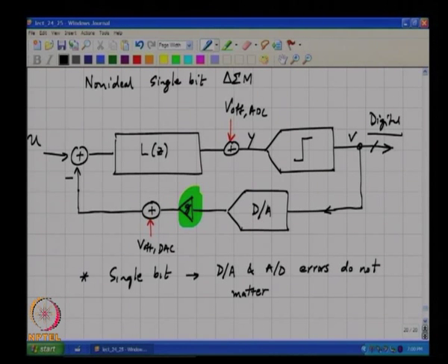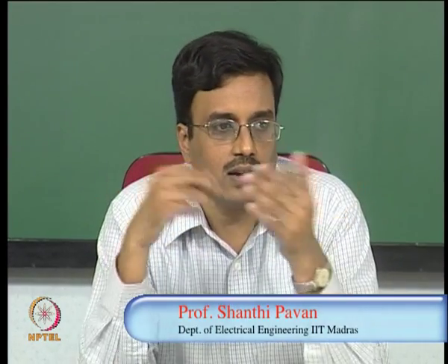On the other hand, in a single bit design, the quantizer design is easy, one need not worry about the linearity of the DAC itself, but the out of band gain can only be about 1.5, and if you want to get a high SQNR, this translates to either increasing the order or increasing the OSR, which is mostly what happens in practice.